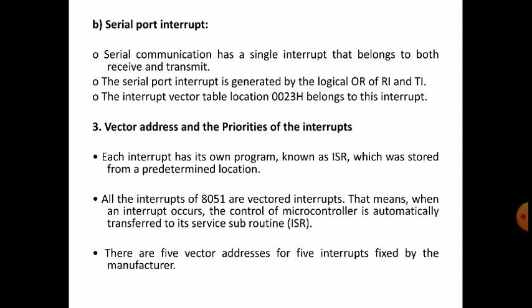Vectored means there is an address assigned to that particular interrupt. If no address is assigned, it is called non-vectored. That means when an interrupt occurs, the control of the microcontroller is automatically transferred to its service subroutine, that is the ISR.